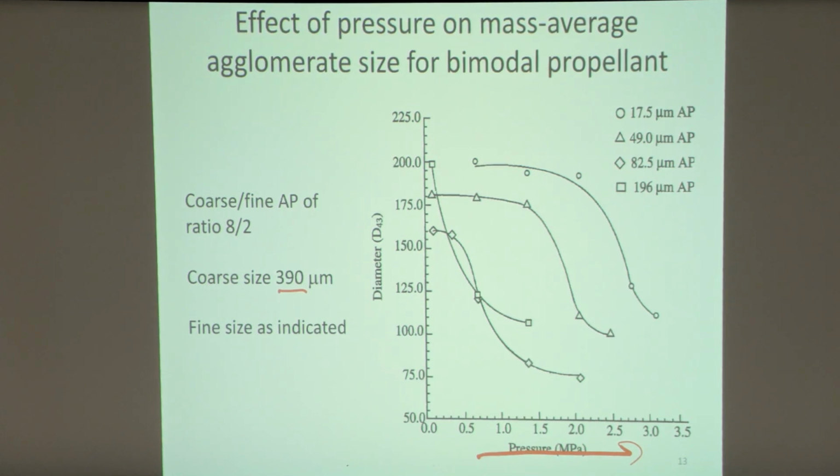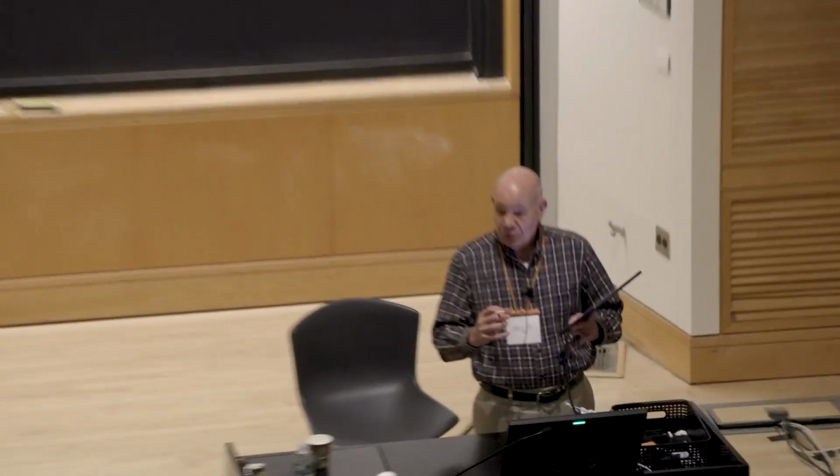The other thing you notice is as I change to smaller particles in between the larger particles, what that means is I'm essentially getting a larger volume for the aluminum to gather. Okay, so they can grow into larger agglomerates, they can sinter easier. Whereas if I have just large and large particles, then the aluminum is better separated from each other, more difficult to sinter.